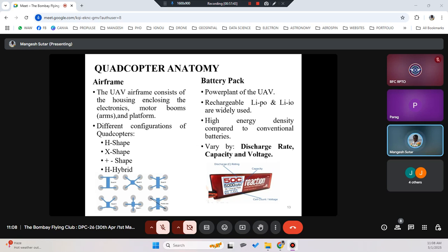So in that scenario, if you're talking about surveillance, if I design a drone which can fly for 20 minutes, and in 20 minutes I'm able to cover 10 acres of land in mapping, I am happy with that. By adding more battery to it, I see that I can cover more area, but whether that is my real requirement or not, and whether I can add a battery or not, because you can't change the battery also a lot of time.